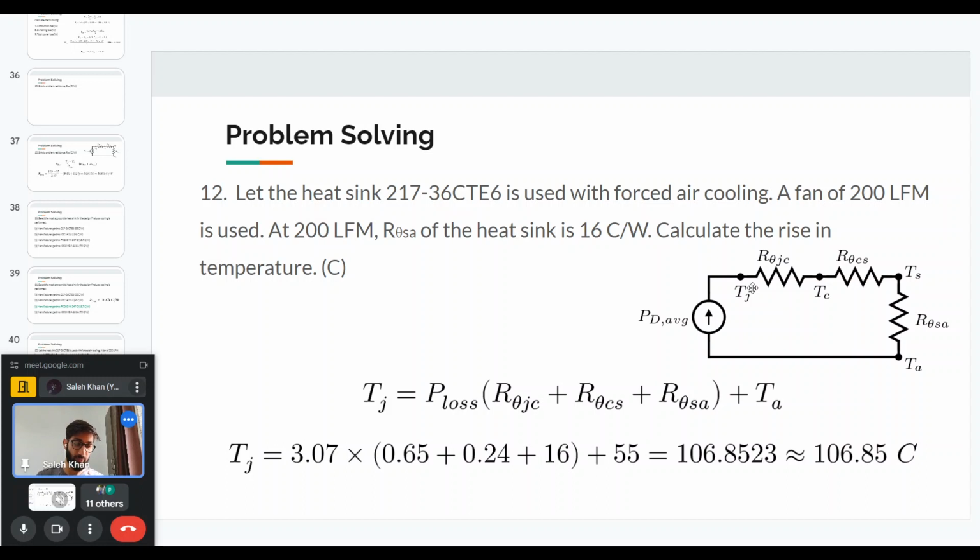In that case, we want an electrical isolation between the MOSFET case and the metallic heatsink, so we have to use an interface material which has electrical insulating properties.